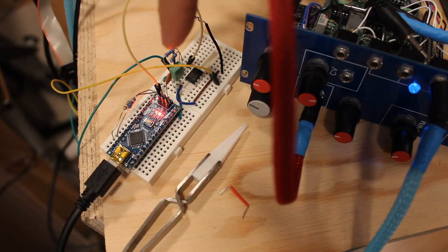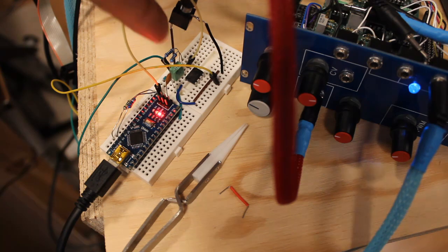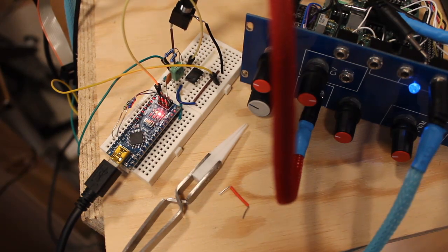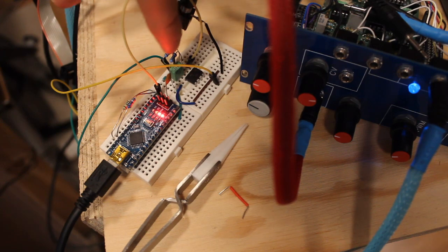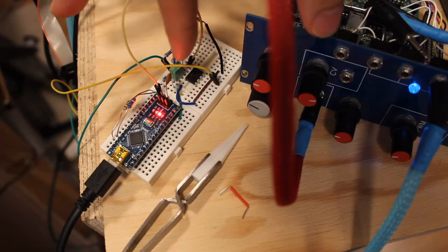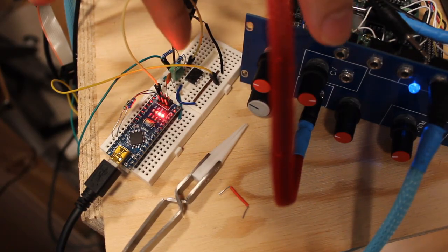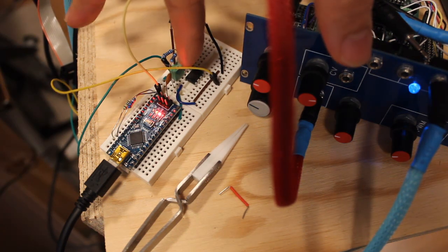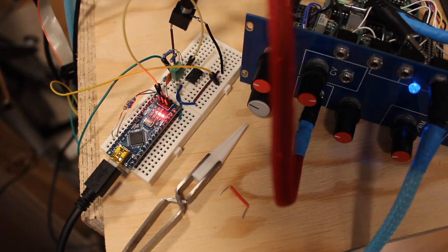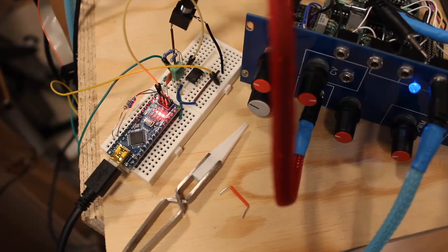So here's the second circuit with the second order low pass filter and the amplification by 2. It happens that you need to create the correct circuit for everything to work and the op amp not to burn up. So here's the correct circuit with a 330 nanofarad capacitor, and as we can hear now, we have a bit longer range, because now it should be around 0 to 10 volts instead of 0 to 5 volts.